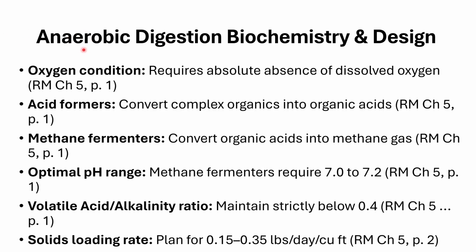Lack of oxygen in this sealed tank. We're going to talk a little bit of biochemistry and design for these digesters, okay? And if you have not taken Professor Gomez's microbiology course, he talks quite a bit about this. He doesn't just deal with water or wastewater, he talks about a lot of the microbiology. I don't remember what number it is in the water series, but it's well worth considering taking if you're really into this stuff, okay? So for an anaerobic, lack of oxygen, digestion setup, we need an absolute absence of dissolved oxygen. The wastewater's got to be void of dissolved oxygen for this to really function well.